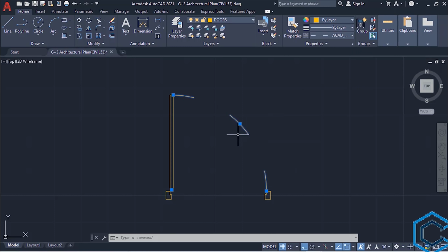of this door like this, left click, and this will create problem once we place it in the plan. So it's better to clip all the things together. We can clip it by 2 ways, either by creating blocks or by creating groups.